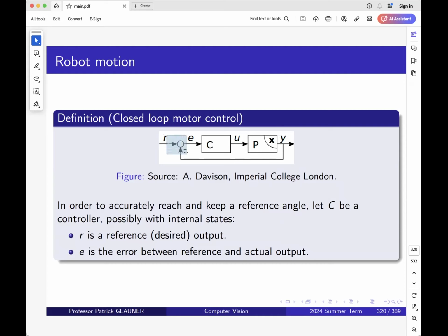Again, then I have a different difference. And then the controller would maybe, in consequence, put a smaller voltage into the open loop motor control. And at some point, this will converge. Initially, it's maybe too low. I put on more voltage, then it's maybe too high. And then my goal is to actually converge.